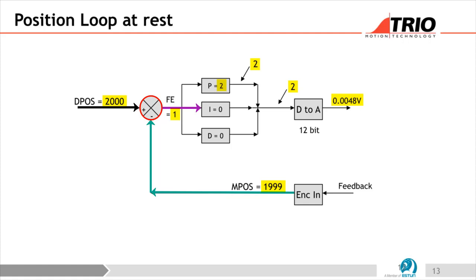With modern systems, it's quite unusual for that not to achieve it. You think, well, 1 count difference is ever so small, but most modern servo motors will correct that. The time it won't do it, for example, is if the motor has some weight on it. If it is a winch pulling something up and there's some mass there pulling it down, you'll get an offset because of gravity, basically. So there are conditions where it won't actually pull in.